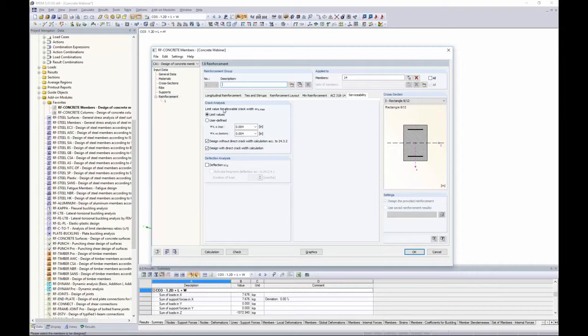Crack analysis. We have the options here to limit the value for allowable crack width based on a couple of criteria. The first option is limit values, and you'll notice in this drop-down box, the ACI did some studies on various exposure conditions and came up with a limiting crack width that they think approximates what the max crack width should be. So for example, if you're in a water retaining structure, your crack width is much smaller than if you're in dry air. For us, maybe we'll stick to something like humidity. The structure is in, maybe, down south where it's quite humid. Same for the bottom. So our allowable crack width is 0.012. Now you also have the option under user defined to just type in whatever you'd like. But we do need to give it some type of limit so that the program knows to flag it if we are over those limits.